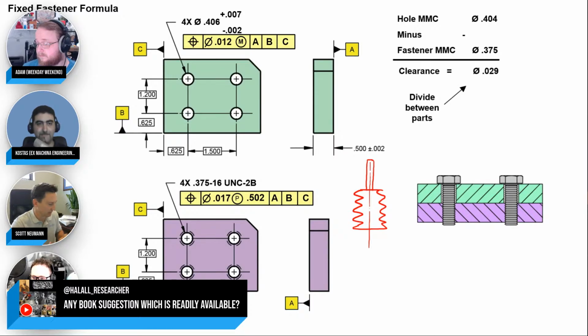Think about that for projected tolerance zone too. You're threading that thing in there, and then what's sticking out is your awesome little ground diameter on the pitch, so you can measure that. Now, the only thing with those is they can be a little sloppy, right? They can kind of rattle around in there a little bit. So some of them have slits put into them, and the slits are constantly trying to expand it. So when you put it in there, it expands because it's got the slit in it, and that takes out the slop, and now you're pretty much centered up on the pitch. That's the axis that you care about.